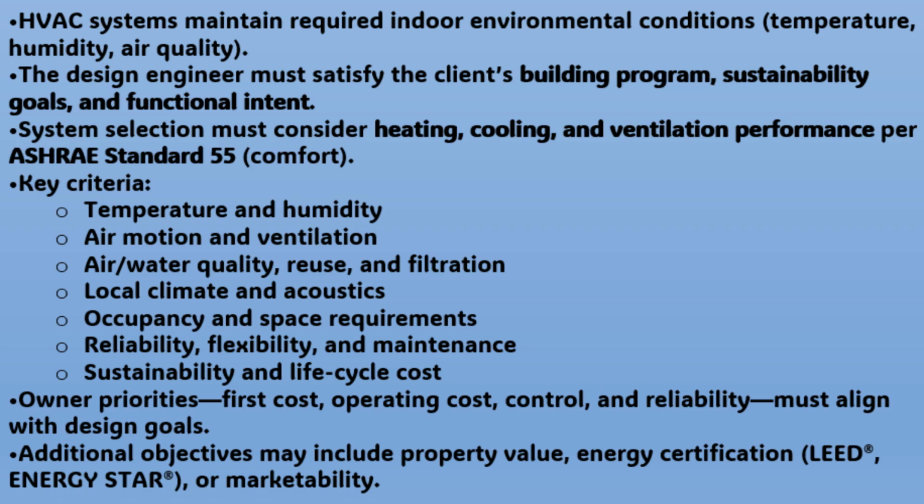ASHRAE Standard 55 defines the comfort conditions we must achieve: proper heating, cooling, and ventilation levels for occupants. When selecting a system, we must also consider factors like temperature, humidity, air movement, indoor and outdoor air quality, acoustics, and even the building's local climate.